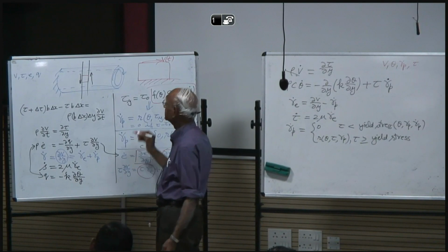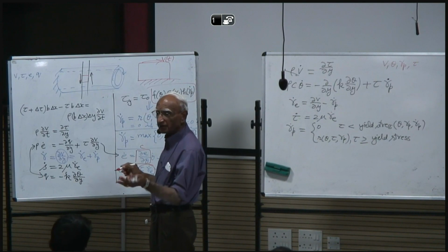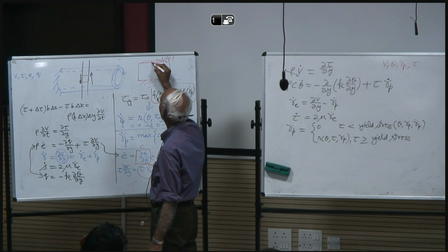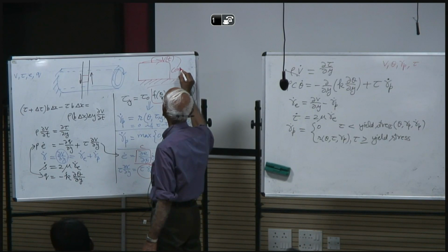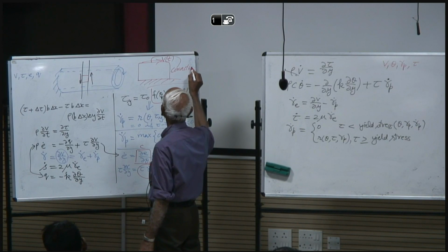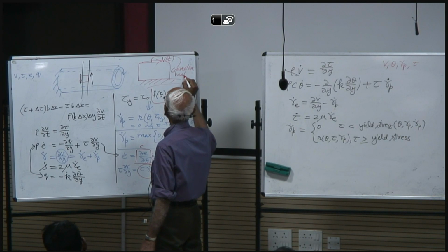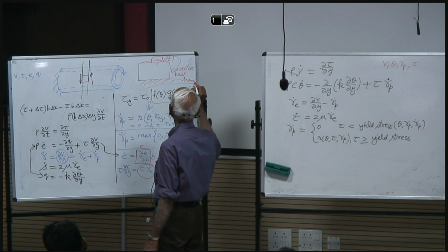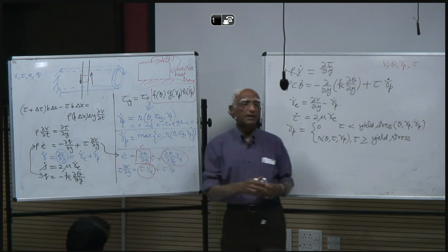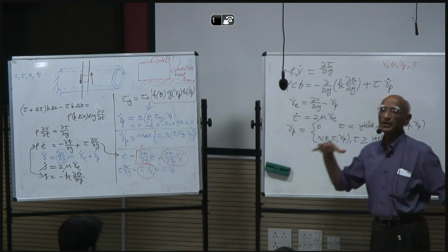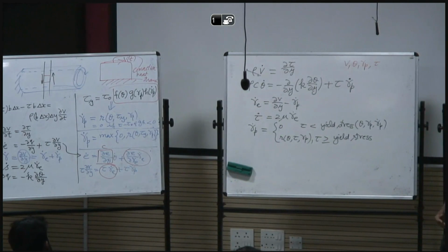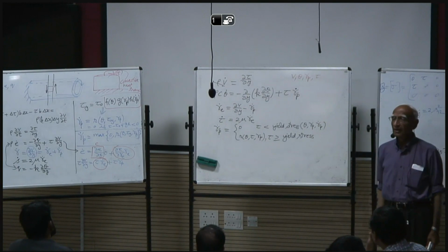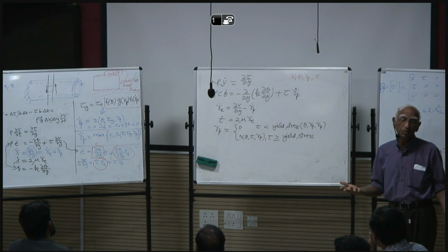Heat flux, if you are interested in convection, then you will prescribe the boundary condition here for convective heat transfer, which means the heat flux will vary with the local temperature, and depending upon the airflow, that can be temperature raised to the power 4 minus the ambient temperature raised to the power 4, or temperature raised to the power 2, I don't know.